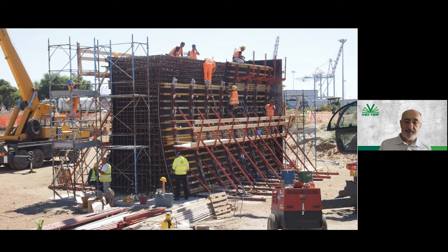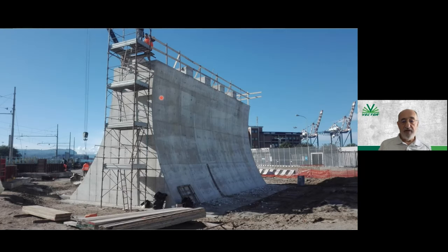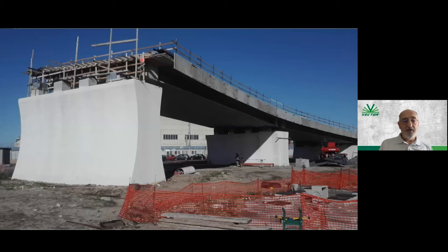they viewed that as the most at risk. So they put a layer of anodes, this is XP4 anodes, all around the top of the steel reinforcement, and then cast the concrete around it. Now you can see from here where the expansion joints are going to be, and therefore that is definitely the susceptible area. My view is that the chloride would also run down to the base, and you would have a high risk area at the base as well.